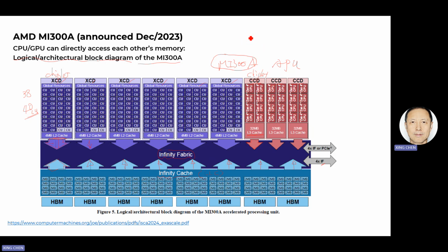What I want to point out is that there is a key difference here. The key difference is that the GPU is no more a PCIe equipment. If you remember in the previous part, we drew the conclusion that with this super chip, the Grace Hopper or the Grace Blackwell super chip from Nvidia, even though the C2C link has been deployed between the Grace and the Hopper, between the Grace and the Blackwell, and we have cache coherency between them, very fast link and cache coherency between the Grace and the Hopper.